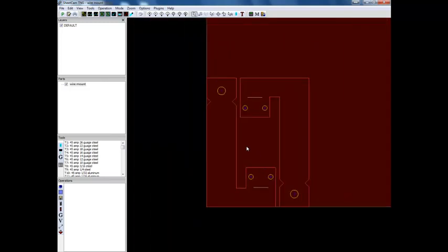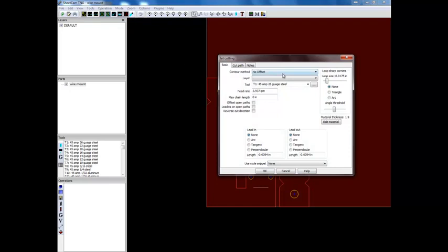Now at this point I'm going to generate a cut for it. So I can go down here to Operation, New Jet Cutting Operations, or I can go up to here and click on the plasma cut. First thing you're going to set is your offset. You set it to outside offset. Now we're kind of setting defaults, and so the next time you pull this up, it will remember what you pulled up.